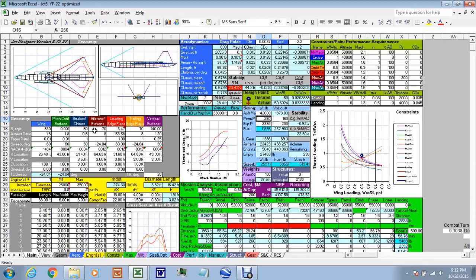We can push the verticals further back so that their AMAX is not coincident with the wing's AMAX, and that's going to help reduce AMAX. That's going to reduce wave drag, and that's going to reduce fuel burn. We've already got too much gas. We can cut this to 40,000 pounds. That's just going to help.